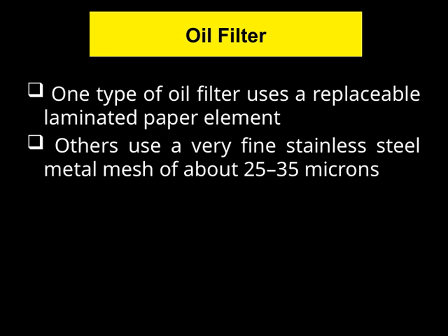Another type of oil filter employs a very fine stainless steel metal mesh, typically around 25 to 35 microns in pore size. This mesh acts as a filter medium that can be cleaned and reused, offering a different approach to filtration. The fine mesh ensures that even tiny particles are captured, helping to protect the engine components more thoroughly.